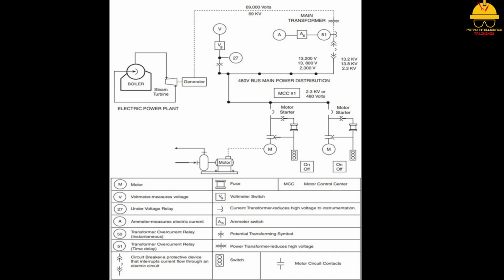Specific safety rules are attached to the operation of electrical systems. The primary safety system is the isolation of the hazardous energy: lockout, tagout permit. Process technicians are required to have training in this area. This picture shows the basic symbols and flow path associated with an electrical drawing. Electrical lines are typically run in cable trays to switches, motors, ammeters, substations, and control rooms.